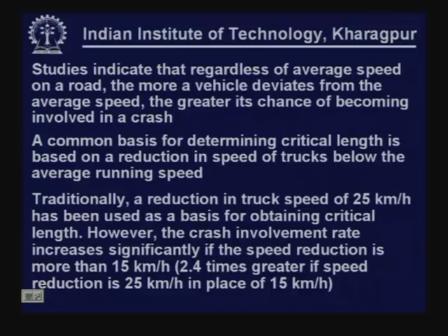Let us see. Traditionally, a reduction of truck speed of 25 km/h has been used as a basis for obtaining critical length. However, the crash involvement rate is found to increase significantly if the speed reduction is more than 15 km/h.